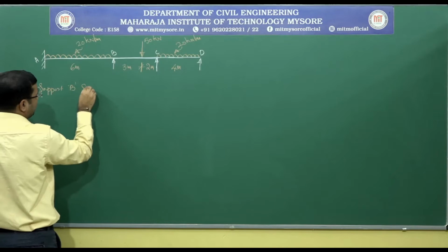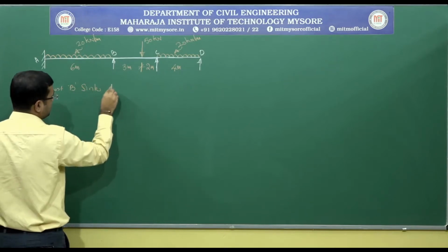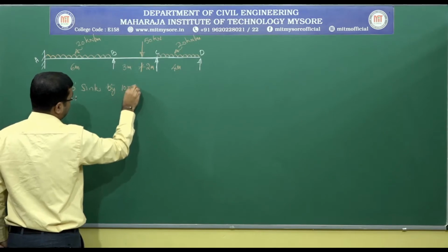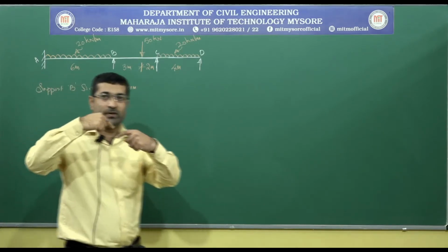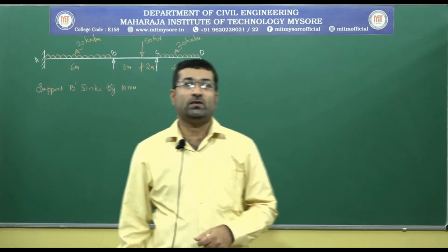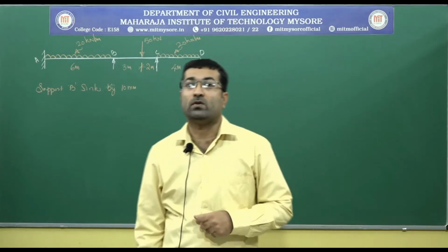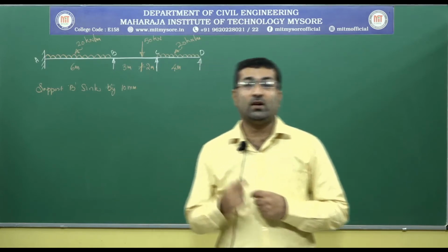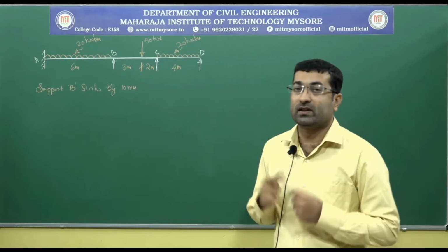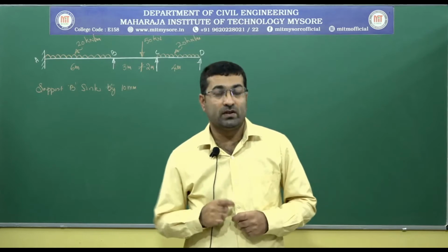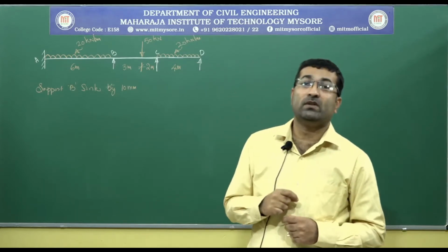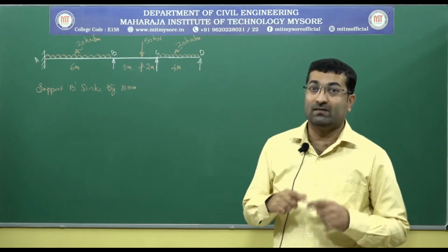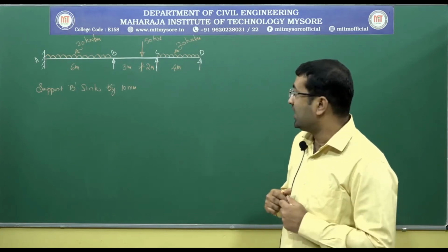And the important thing is the support B sinks by 10 millimeter. That is, the support point B is sinking down by 10 millimeter from its original position. So, when a support is sinking, obviously the development of bending moment will be different. We have to observe how, just because of this 10 millimeter sinking, the shear force and bending moment pattern will change.